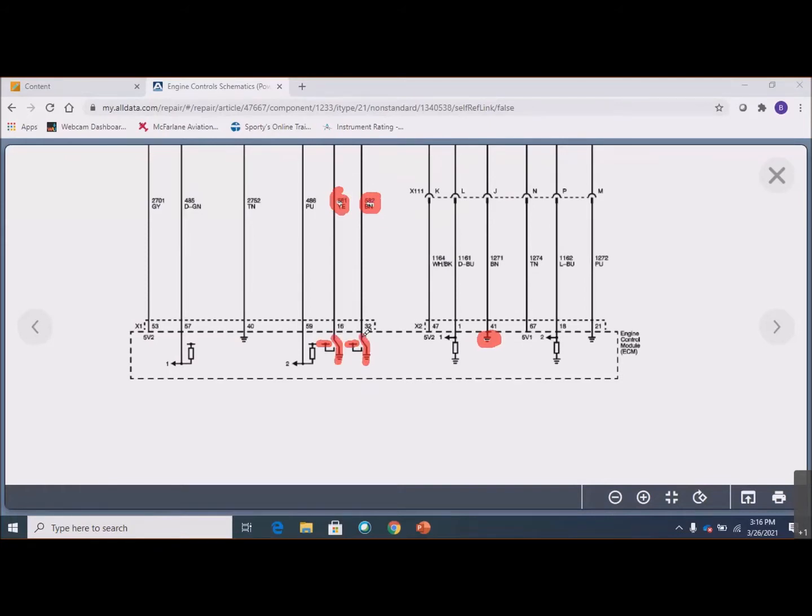That's their default position. So if the engine control module desires to operate that motor, all it has to do is take one of these, let's say pin 16, circuit 581, the yellow one here, and connect it instead to power. Unhook it from ground, connect it to power, and leave the other one connected to ground.